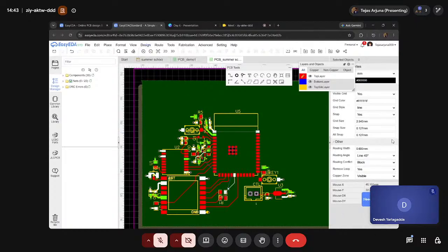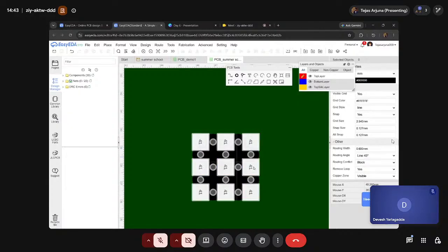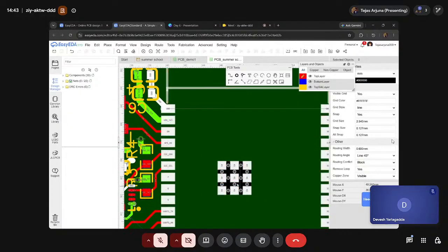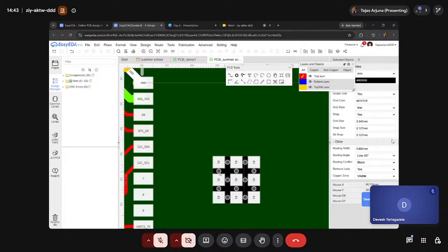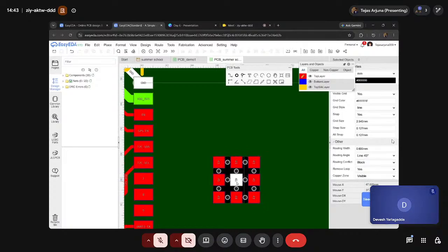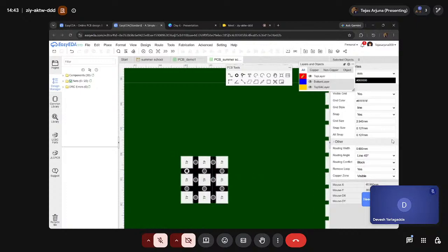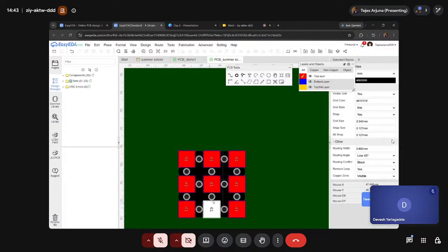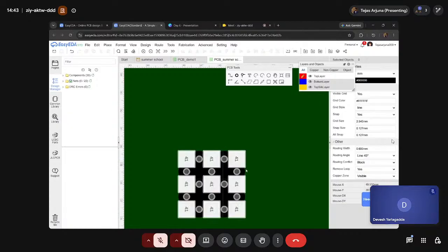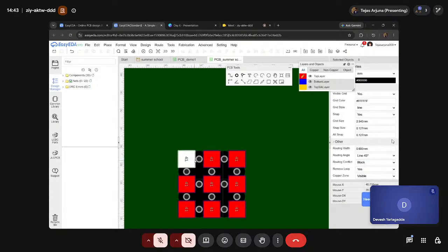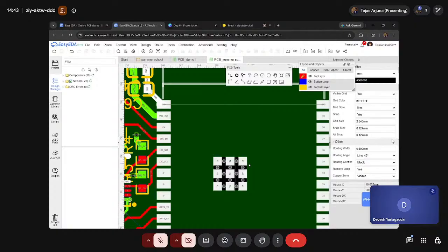We need to make 2 more connections, and why? Okay, we are seeing these things, right? These are called the thermal wires. Satvik had explained this in the third session. These are thermal wires for dissipating heat, and these pads are for making the surface distributed to make the heat dissipate through a larger area.